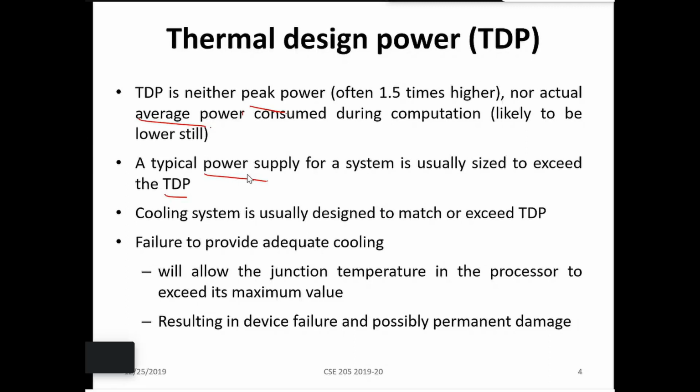So we need to determine this metric first. This TDP has to be determined, and accordingly the power supply system and the cooling system have to be designed. The power supply system should exceed the TDP, and the cooling should either match or exceed the TDP.